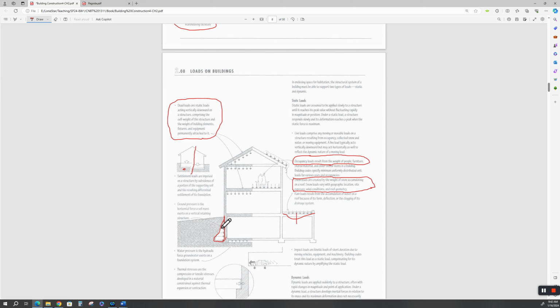Now to build this, remember what I said? We had to excavate back away. I'm a big proponent of this. I've seen a lot of contractors screw up. It's one thing to dig this area out and then put this wall back in, but what happens? You pull all this load off of the foundation, off the existing soil down here. This might actually rise a little bit. It might expand up a little bit, but then you got to put all this back in.